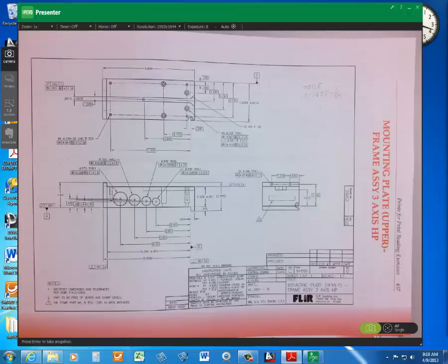Usually in industry, in manufacturing, machining and machine assembly, that's common as dirt. If you've got a counterbore, there's going to be a socket head hex screw going down in there that you use an Allen wrench on.